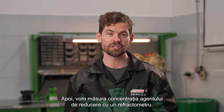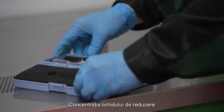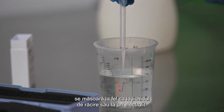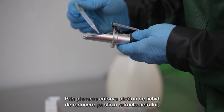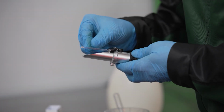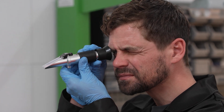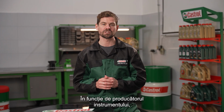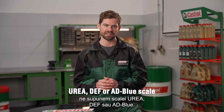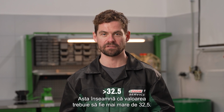Next, we'll measure the concentration of the reducing agent using a refractometer. The concentration of reducing fluid is measured in the same way as a coolant or electrolyte. By placing a few drops of reducing fluid on the refractometer glass, we can measure the concentration value of the fluid. Depending on the manufacturer of the instrument, we use the urea, DEF, or AdBlue scale. This means that the value must be greater than 32.5.